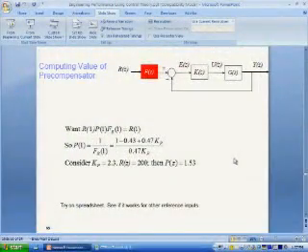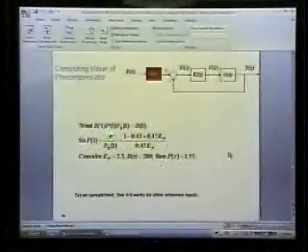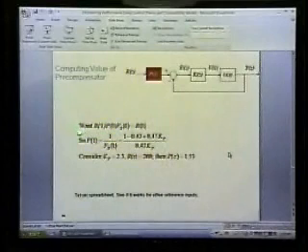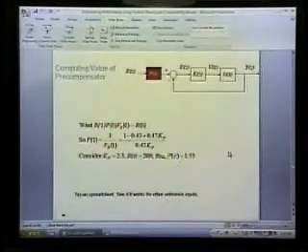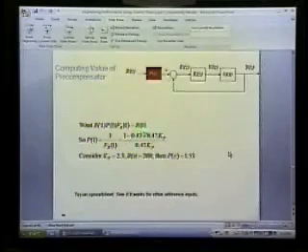When you think about what the precompensator is doing, you're primarily interested in how it affects steady state gain, right? That's what you're interested in. So what we really want is that the transfer function times the reference input, which will be the measured output, times the precompensator is going to equal the reference input.